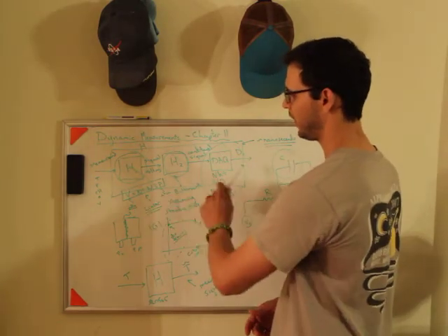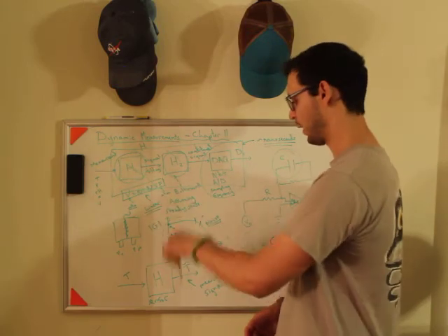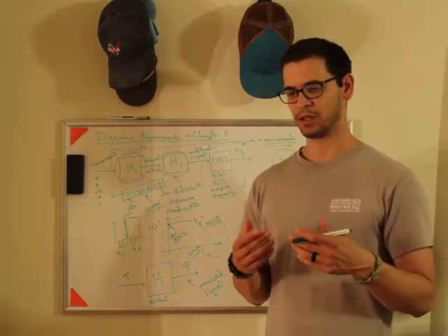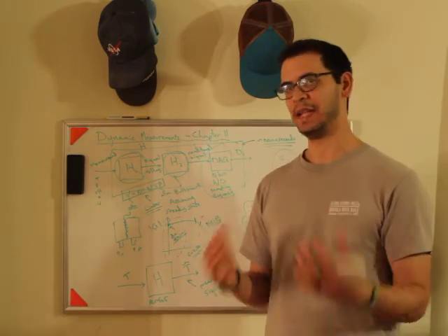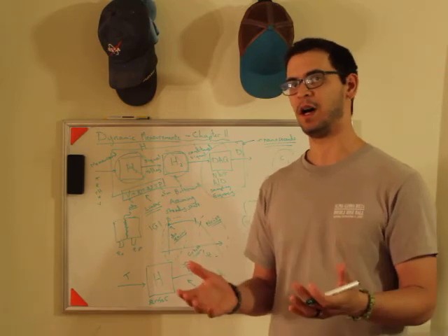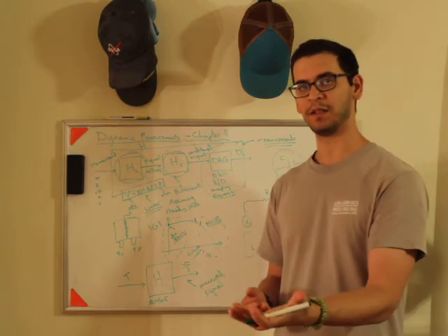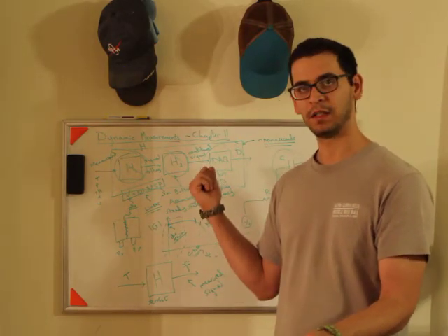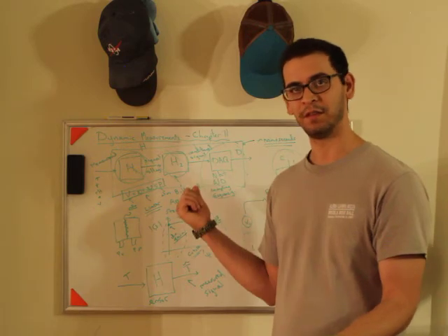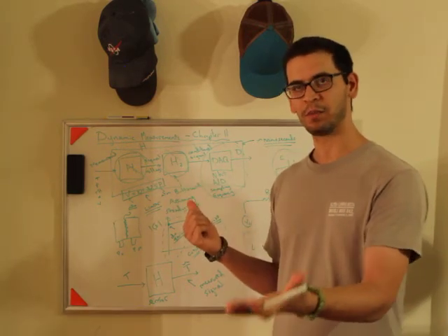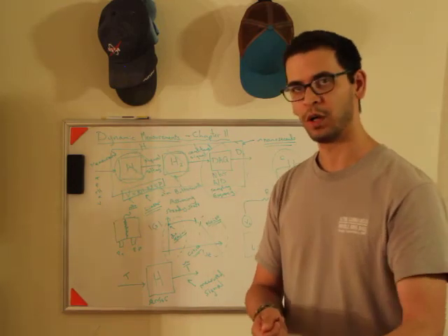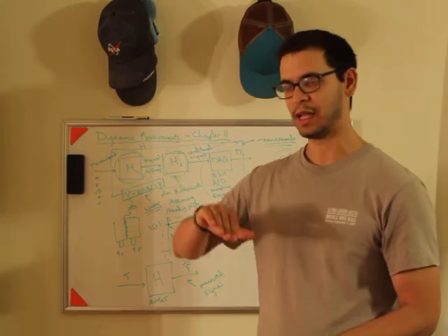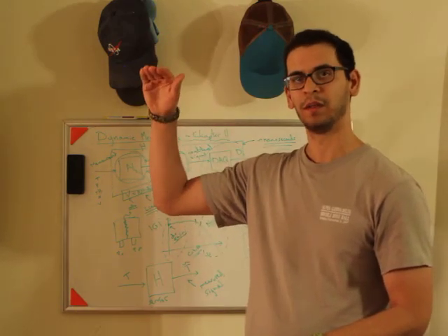Now, in the past, we may have assumed that this was linear, but what we're now going to do is assume this is dynamic. And the best example I can describe is, imagine you are in your house and you've AC'd the house down to 68 degrees. Somehow you have an awesome AC system. And you have a temperature sensor that's reading 68 degrees. Outside, you're living in the south, and it's 95 degrees. If you take that temperature sensor and just open your door and immediately walk outside, your temperature reading is not going to read 95 degrees. It is going to take time to slowly ramp up, okay?